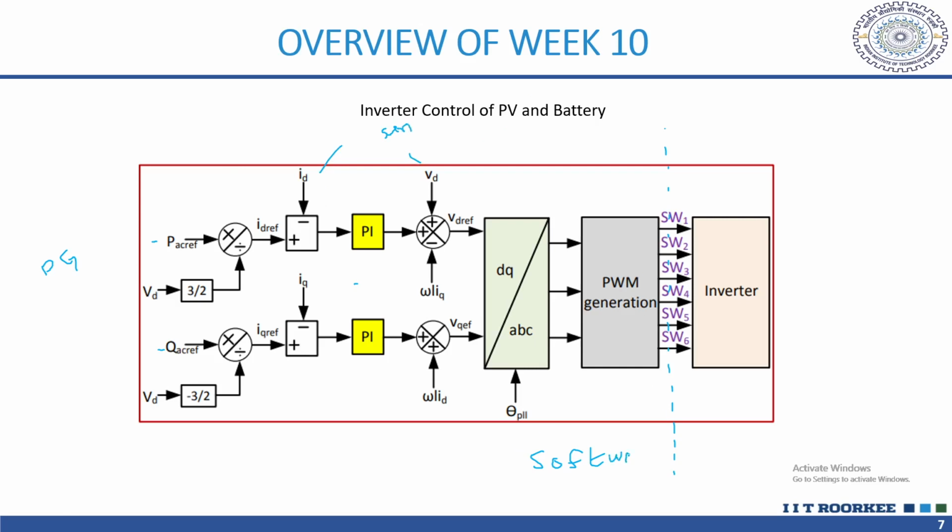This algorithm will be run in the software that we had studied under the RTDS or OPAL-RT platform. Then these pulses can be sent to the hardware, the actual inverter. So that is how we work in a lab setup basically.